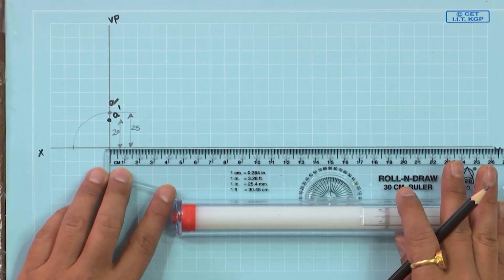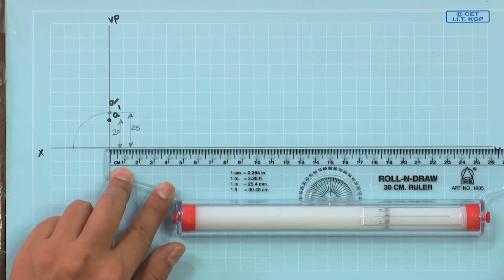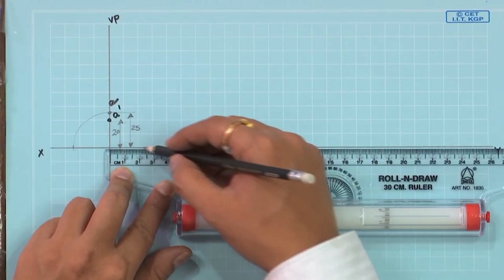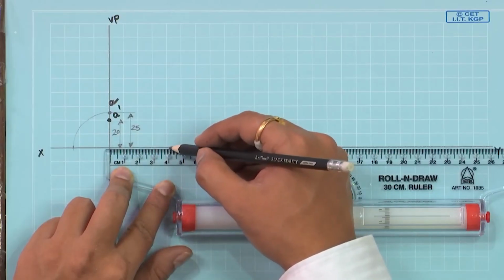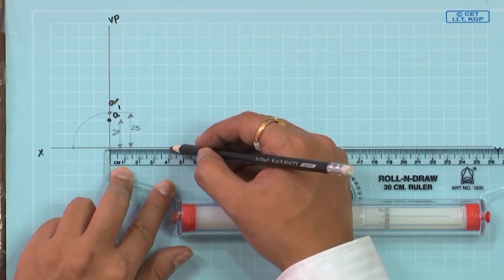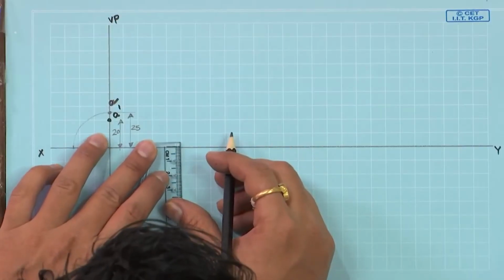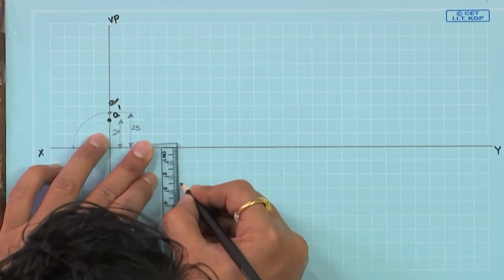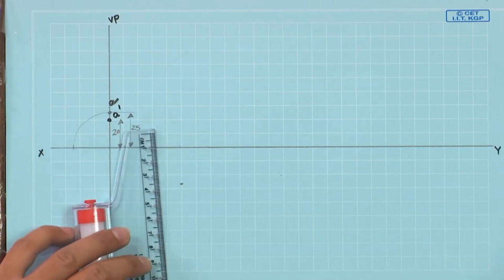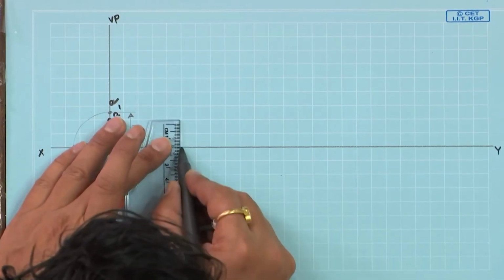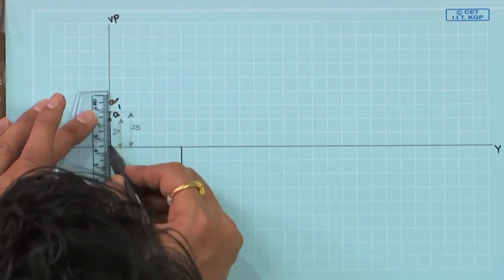So, leave some gap, and if you are looking at this sheet, a minimum 30 mm gap has to be given for any construction of the projectors. From the projector 30 mm I have to give, and go ahead and construct this below 25 mm. So, somewhere here below 25 mm, mark a point, call this one B prime, connect these lines, this is the front view, this is okay.